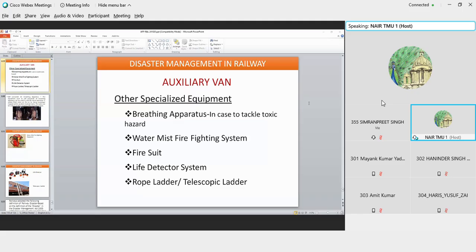So these are basically destabilizing forces, and instantaneously you may find a situation where this destabilizing force has become much higher than the stabilizing force. Then the wheel would either jump out of the rail like a sudden derailment, or it will start mounting the railhead. And that happens especially in the case of positive angularity.